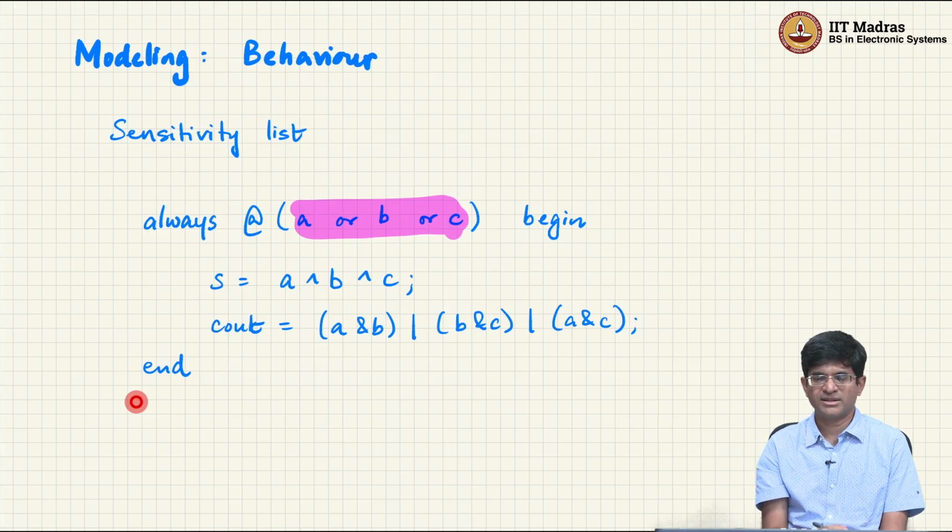Why this is important is, you should always keep in mind that your goal over here is not just to write functions or similar code that somehow passes a test bench. You are actually trying to create hardware or model hardware, which means that you need to have the end goal in mind. What should your hardware look like? And then write your Verilog modules to achieve that functionality, right? And once you do that, automatically what you get out of it is basically RTL. You don't have to think more in terms of is this RTL or is this the right way of doing it. It will be RTL, it will be synthesizable, it will give you hardware because you started with the mental model of hardware in the first place.